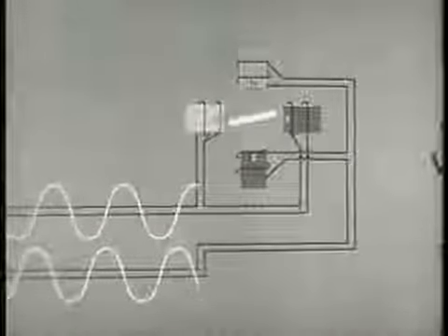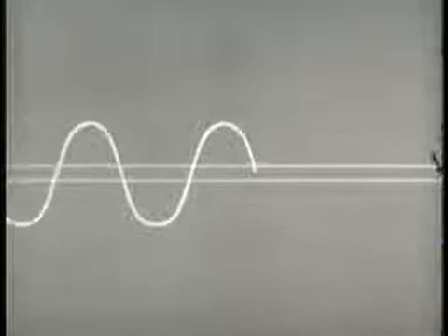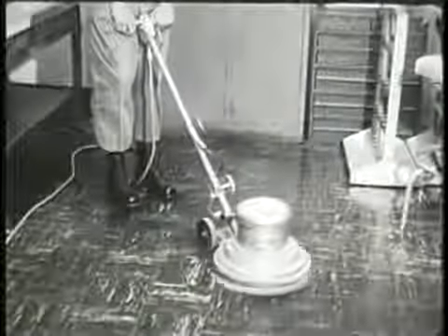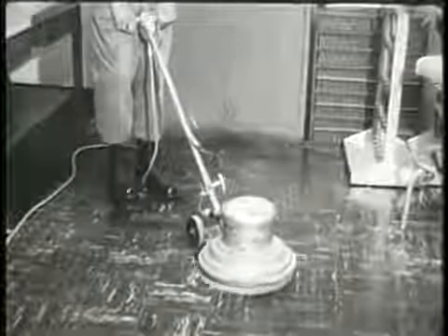This rapid change of direction is accomplished simply by reversing the polarity of only one set of poles in the motor. The polarity of the second set of poles will remain unreversed. The field will now rotate in the opposite direction, with the rotor following at a slightly slower speed. The most common type of current available in most sections of the country is single-phase AC. For that reason, single-phase induction motors are widely used for many and varied purposes.